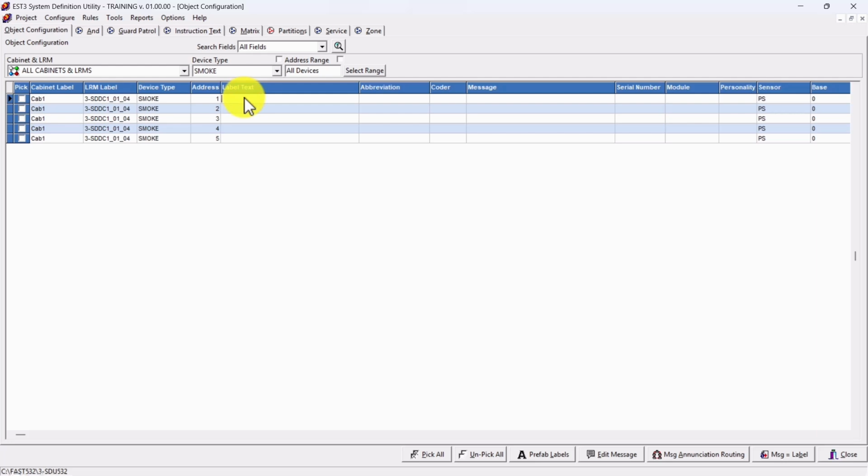Some systems, when you're doing custom controls, rules, programming, whatever you call it, you can manipulate the fire alarm programming either with the address, like M1-1, do this, or you could manipulate the fire alarm control rules with the label text. How Edwards works, you have to label each of your devices with a specific label. So let's say you had 500 smoke detectors, you wouldn't want to do this individually. What you would want to do is down here, you see you have some information down here. We could pick all. So now we select all of our smoke detectors within this one smoke detector device type group.